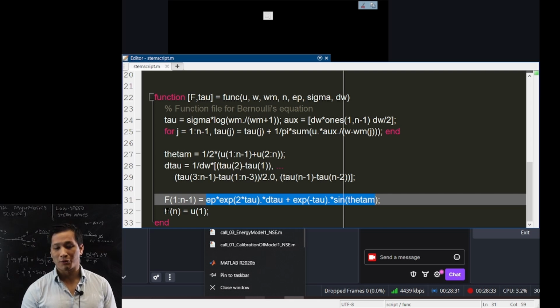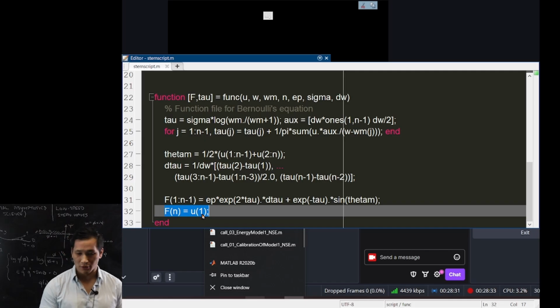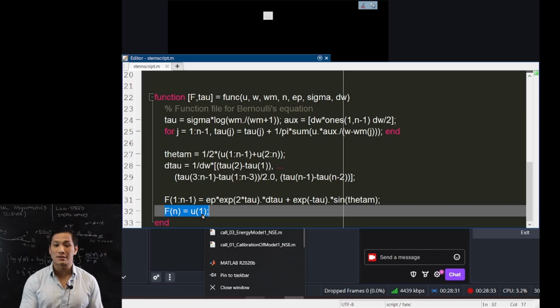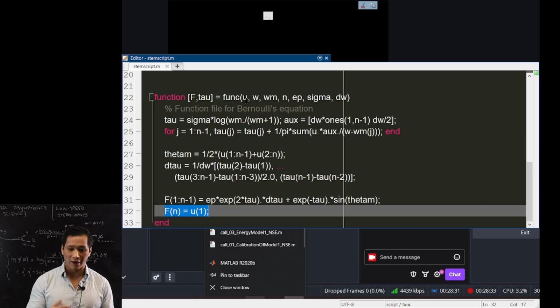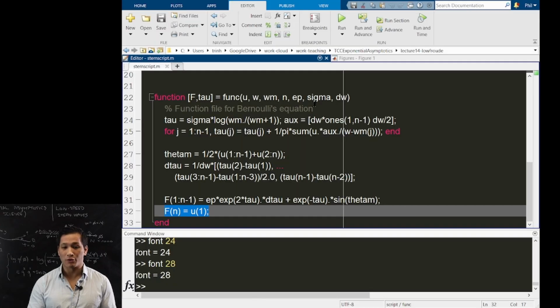Okay? And then you go and replace the last mesh point with the fact that you need theta at 0 to be 0. I wrote that you needed q at 0 to be 0, which turns out to be true, but because your system of equations is in theta, you're trying to solve for the theta values, and you get the q from the integral equation, I've put my boundary condition down here as theta. Obviously, this is something that requires some thought. You're not meant to understand everything right away, but you can see how it's done and how it can be done quite compactly.